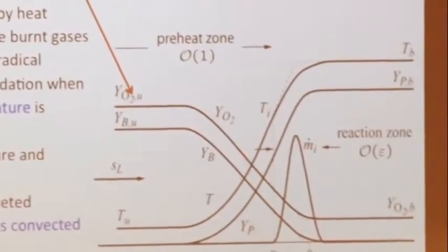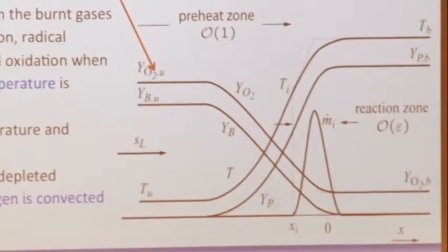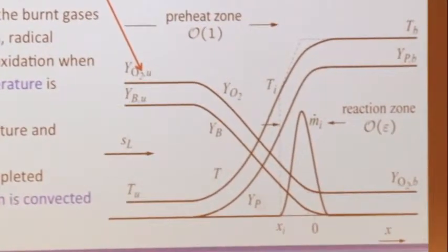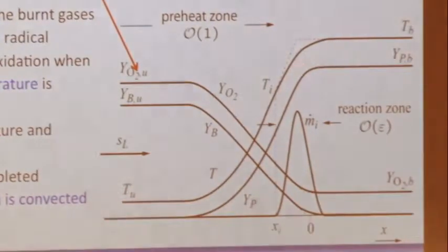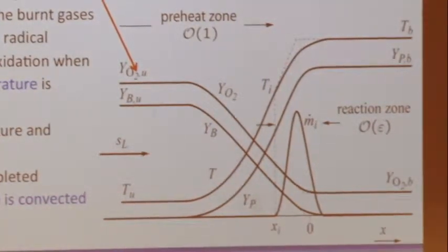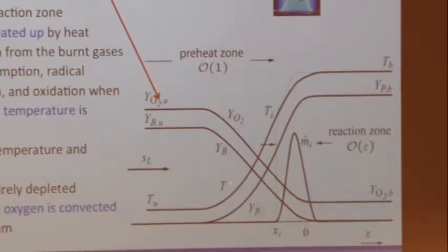They are convected towards the flame. They don't burn because they're cold. And so while they approach the actual flame front, they approach this region of high temperature. And because the temperature in the unburned is low, and in the burned it's high, you have diffusive thermal energy flux or heat conduction from the burned into the unburned, which basically heats up the unreacted gases.